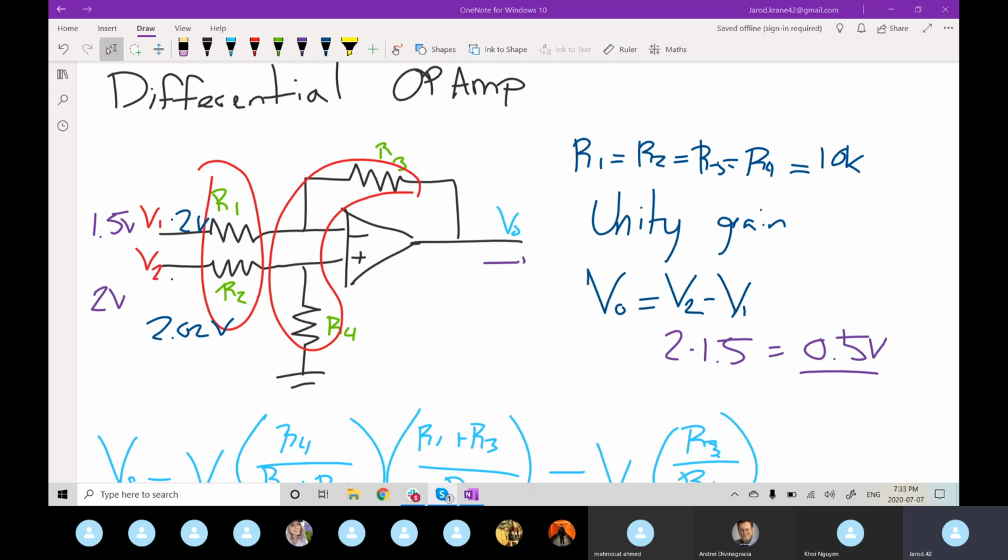Yeah, that's also how you do current measurement with shunt resistors? You need some sort of common mode rejection. Yeah, that's the other thing. Current reading is typically done just through a shunt resistor.